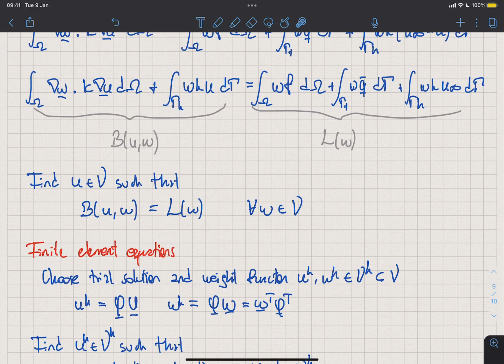So when I do this, this U is going to turn into a UH, this W is going to turn into a WH. So now I have to apply the derivatives of shape functions, and here the derivative of the shape functions is basically the outer product, and that is going to form a matrix in the implementation already of the local stiffness matrix.